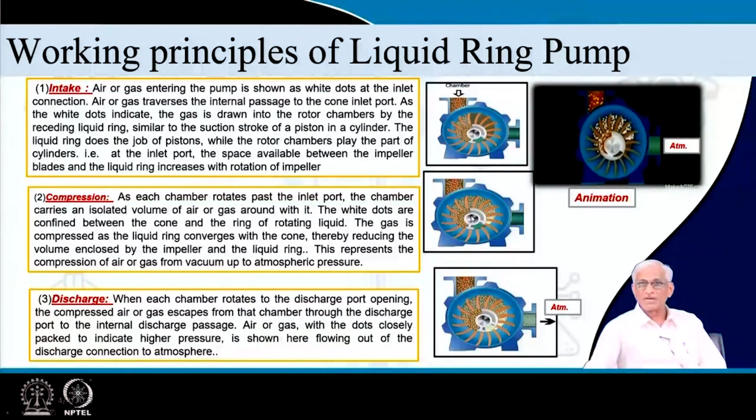When they are entering, why are they entering? Because the chamber volume is increasing this side, increasing volume for the same number of moles, pressure decreases. Because of that, more and more molecules will be sucked into various chambers. You can see that here. The molecules are automatically sucked through this wall into this increasing volume. Look at this animation. And after some time, when it comes to this portion, the inlet is isolated now.